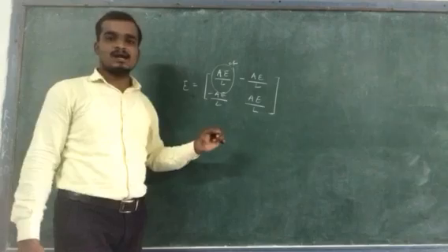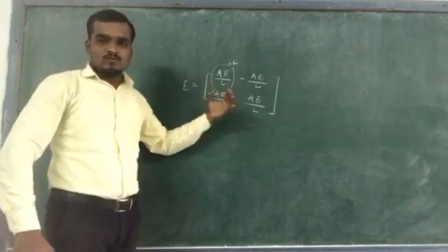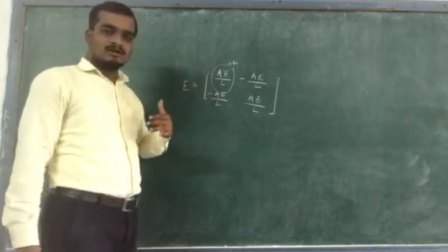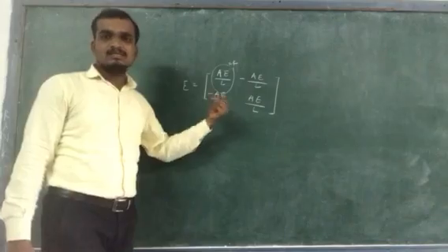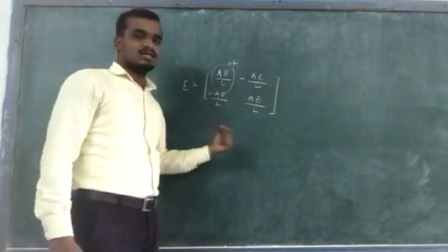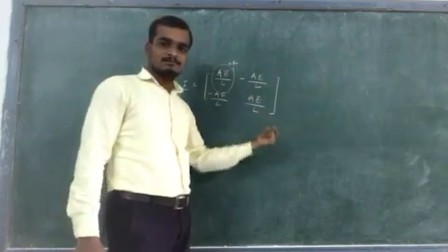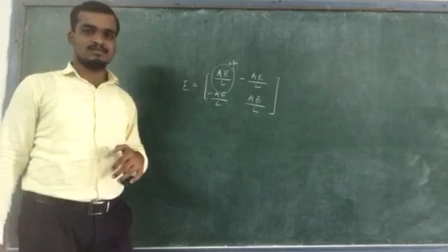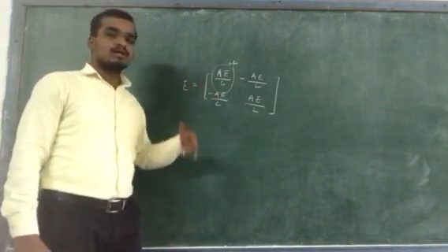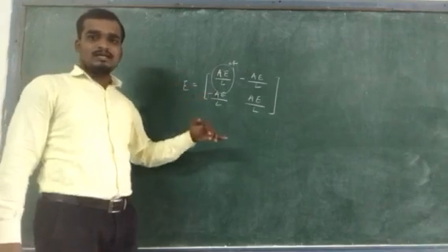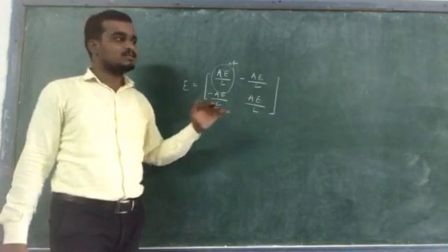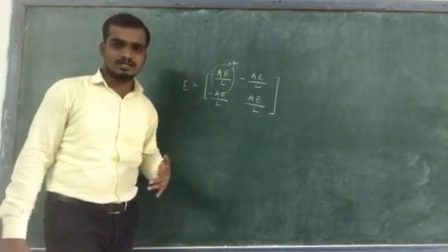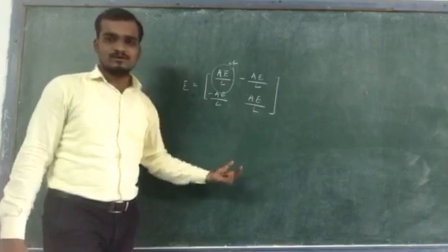Third step is to apply the boundary conditions. As we applied the boundary conditions in our spring system, in a similar way we will apply the boundary conditions to the bar system: apply the boundary conditions for the force vector as well as for the displacement vector. Then apply the elimination approach to get the displacement values first. By applying the elimination approach, you will get the eliminated equations only, meaning 2 or 3 equations. By solving these 2 or 3 equations, you will get the displacement values first.